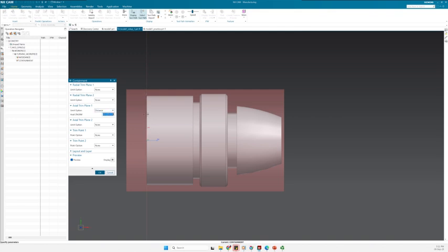So if you don't want to put any cutout, perhaps this would be, for example, that you have 5 mm available. But if you want to put some cutout, we can put, for example, 15, or it's a bit too much, or 10, and then you have enough part to be clamped. But these are the things that you should be calculating and deciding beforehand.